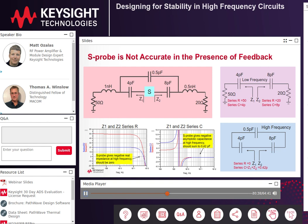in any design tool. To demonstrate this, we have a very simple passive circuit demonstration that shows the difference between the behavior of the old S probe and the new WS probe when subjected to feedback within a circuit. If you study the circuit shown, you see it has obvious low frequency and high frequency asymptotic behavior that can be understood largely by inspection. From the probe's perspective embedded within the node, the low frequency looking source impedance will basically look like a 50 ohm resistor in series with a 4 pF capacitor. In the load looking direction, the probe will see a 20 ohm resistor in series with an 8 pF capacitor.